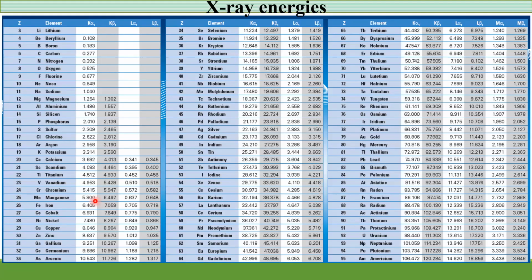But if you have a real manganese peak of K alpha, it should have a peak intensity more than that one. But sometimes it also has the K beta of chromium within the peak region. So only the recent advanced systems will try to identify those things. Otherwise, whatever chemical quantification you do with some percentage, it's not actually the real one.